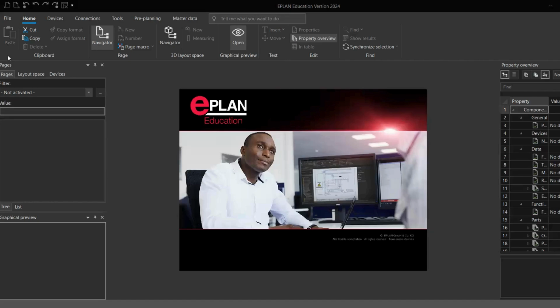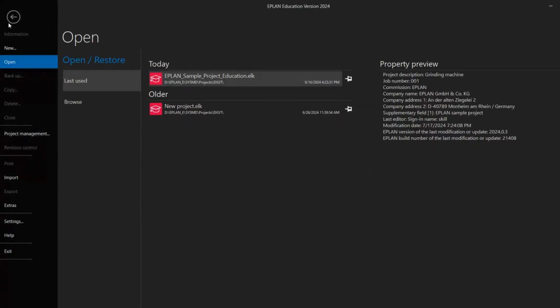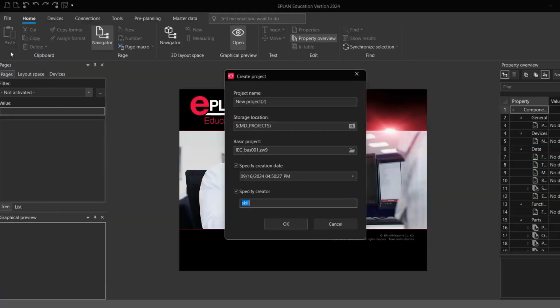In this video, we are going to see how we can create new projects in EPLAN. For this, we need to go to the File tab, then click on New, and then we can enter the name. So for example, EPLAN sample project. That's the name that I am entering here.